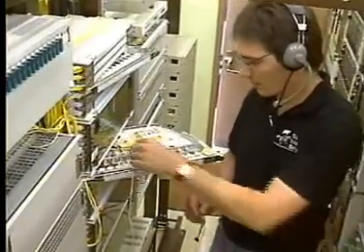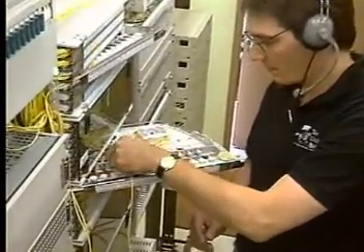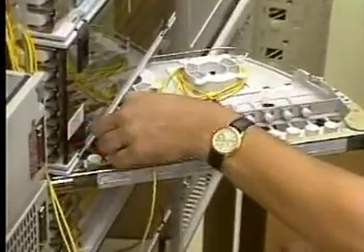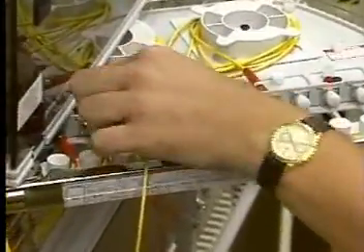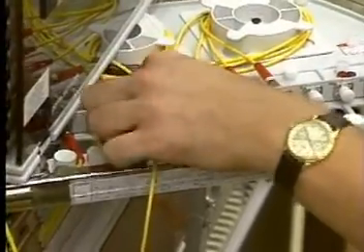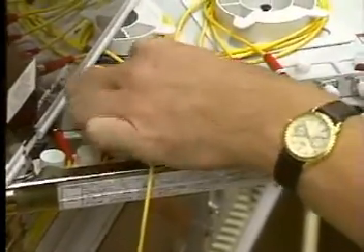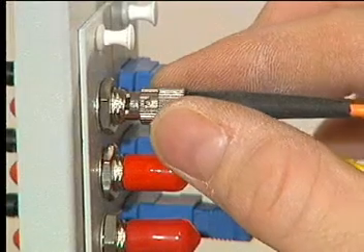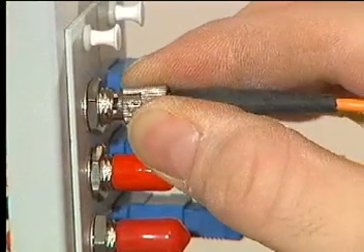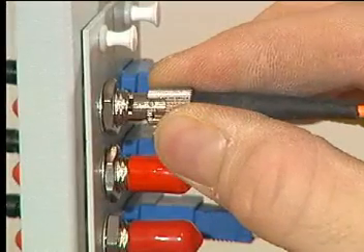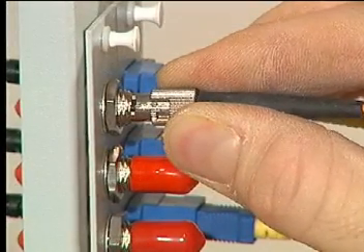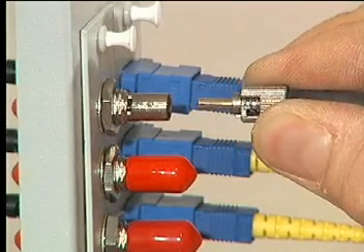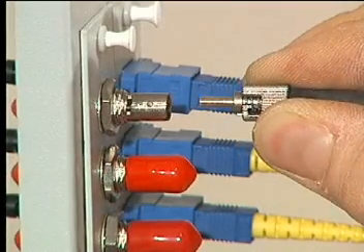When connectors are mated repeatedly, normal wear can shave tiny flakes of metal from the internal alignment sleeve, as well as very fine ceramic dust from ferrules. This material may accumulate and contaminate the connector. Another point to consider is that every time a connector is pulled from its mating sleeve, a vacuum is formed within the sleeve that sucks in contaminants that may be floating in the air nearby, so the more you mate the connection, the dirtier it gets.